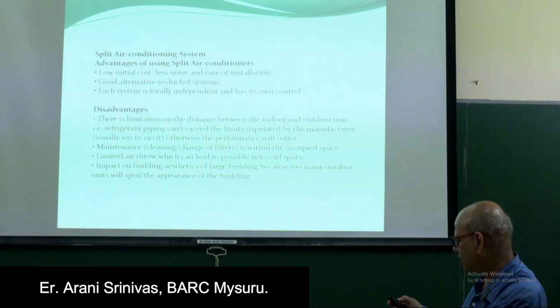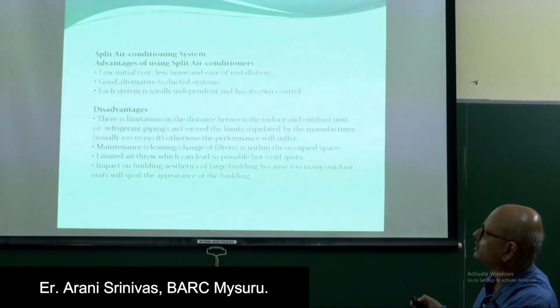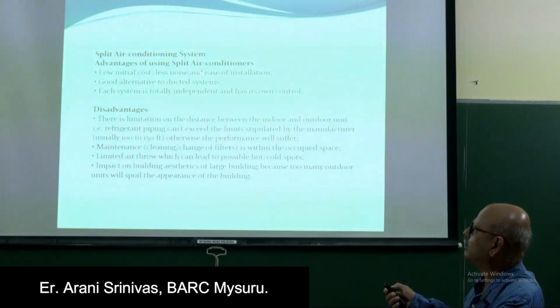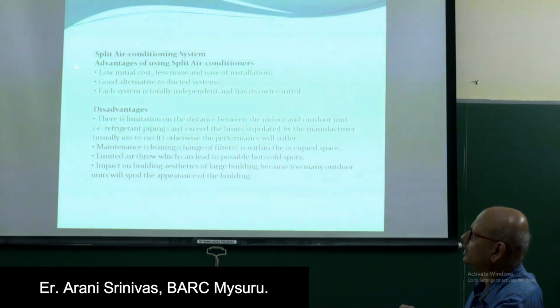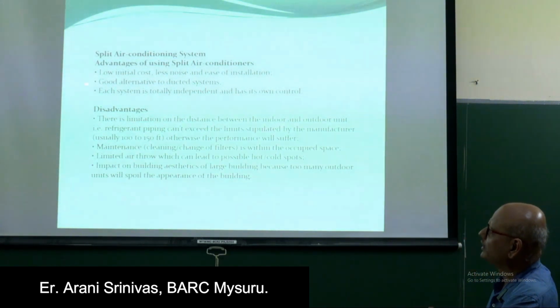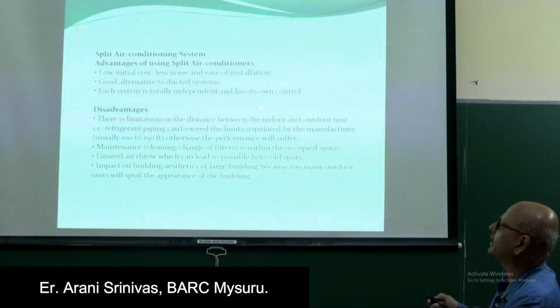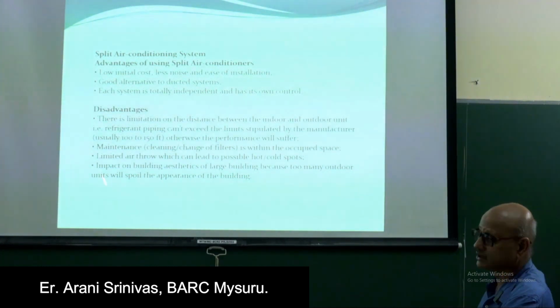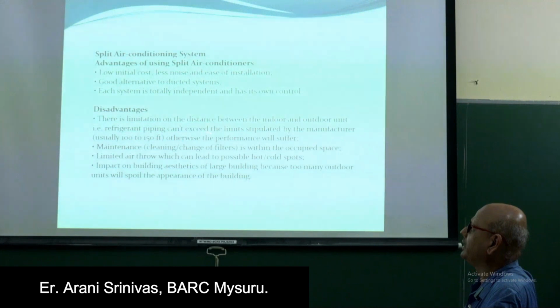So in split, the advantages are low initial cost, less noise and easy installation, and it is a good alternative to a ducted system. Each system is totally independent and has its own control. The disadvantage is that there is a limitation on the distance between the indoor and outdoor unit.